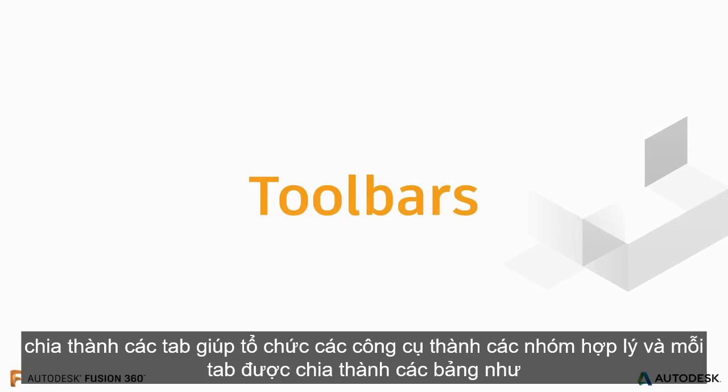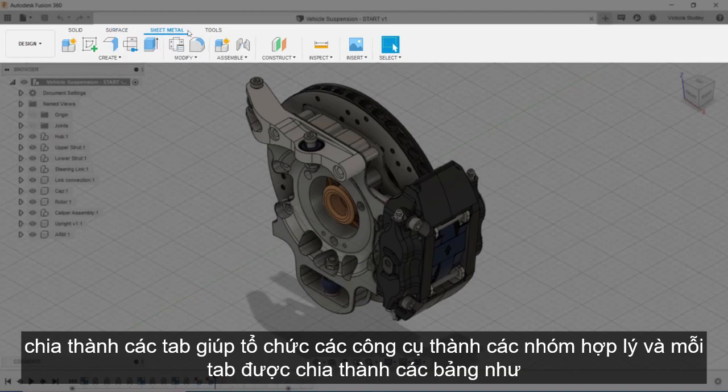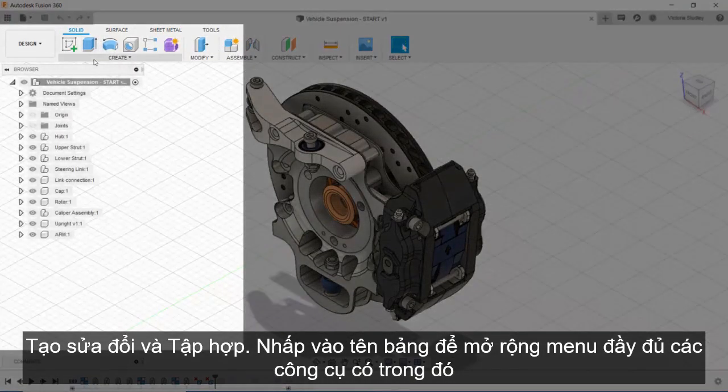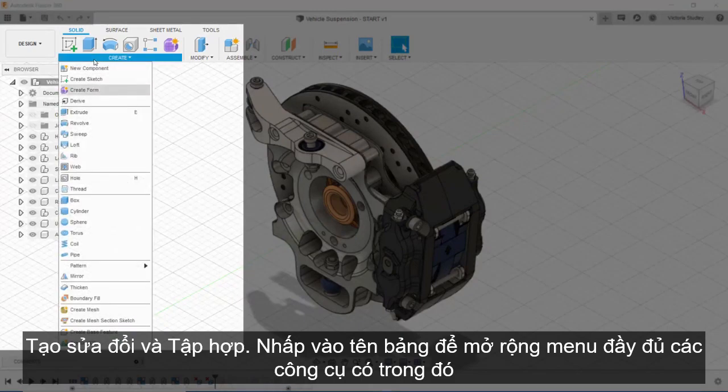The toolbar is divided into tabs that organize tools into logical groupings, and each tab is divided into panels like Create, Modify, and Assemble. Click the panel name to expand the full menu of tools contained within it.